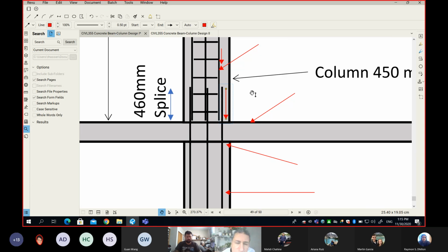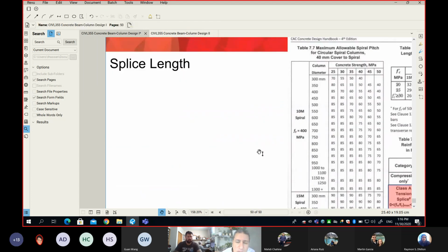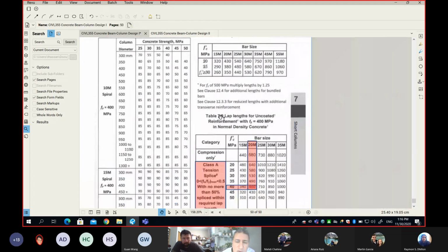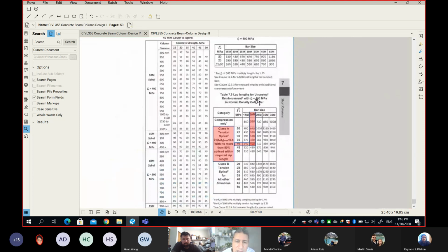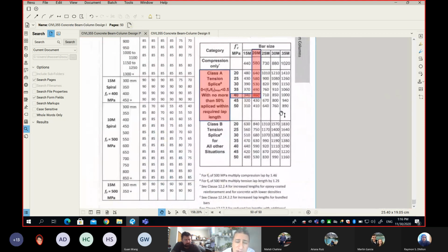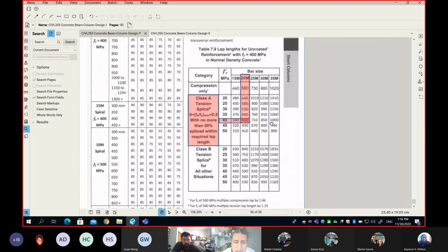Okay. How do we do that? We do that through the bond. So the concrete is simply wrapping around those bars, and the concrete will transfer the load gradually from this bar into the bar going to the column below. Now, when you think about this process, I'm going to explain the factors for you, and it could be one of the theoretical questions on the final exam.